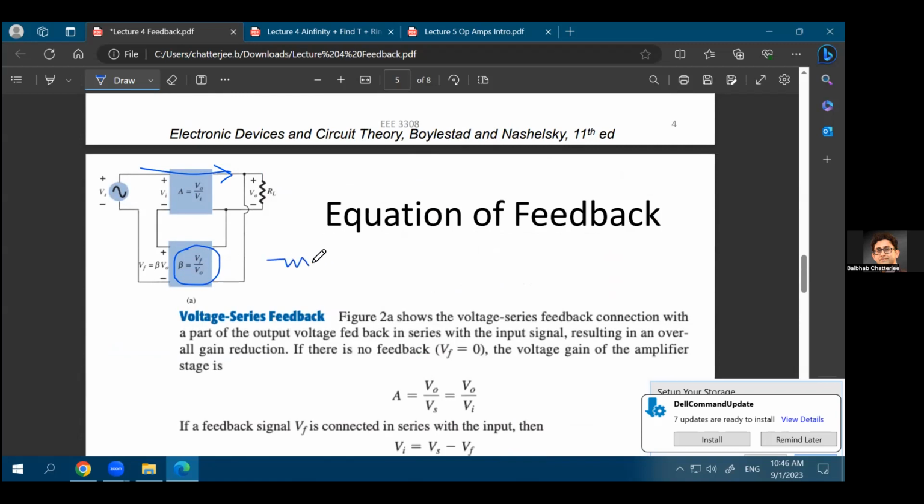So let's say you already have seen how resistive dividers look like, right? This resistive divider, where your signal is coming from right to left in this case, if you have two resistors over here, R1 and R2, they will create this resistive division between R1 and R2. So you'll have a feedback factor of beta, which is less than 1. And this is something you have solved in your homework 1, that if you have this resistive division, your gain is less than 1, right? So your beta is something that is less than 1.